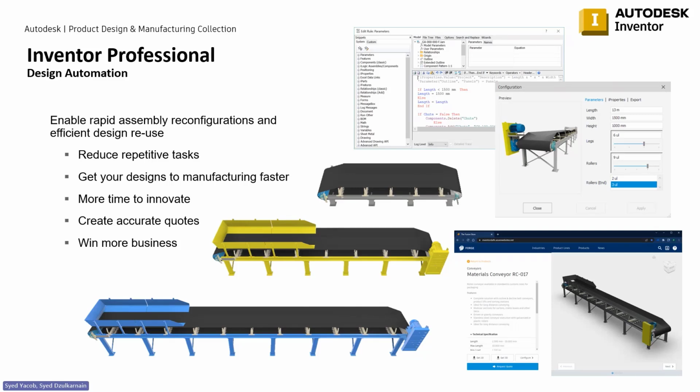Okay, design automation. This is fairly unique to Inventor, because from your design you can actually automate your design. Let's say we're talking about very simple products here, a box. One box probably does not have many different designs. Probably the differences are more in the stamping and the exterior, but I can say most of them are in the sizes. So you can just create one model and control the sizes using a form. You don't have to go in and change dimensions or details directly in the design part. You can just use a form to change. Even your normal salesperson can help to do this.